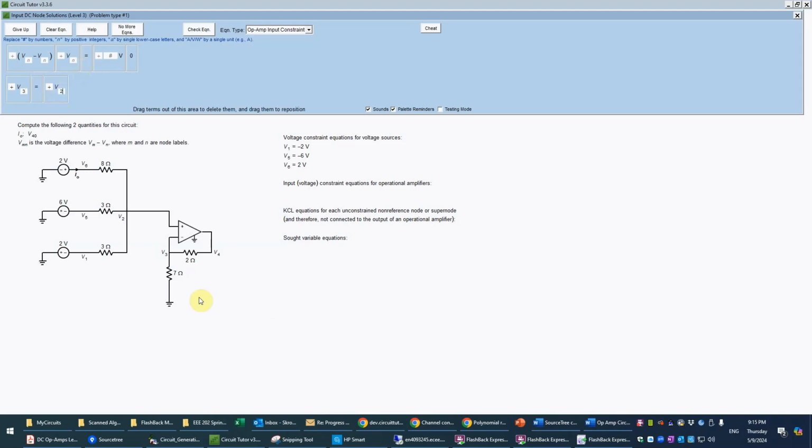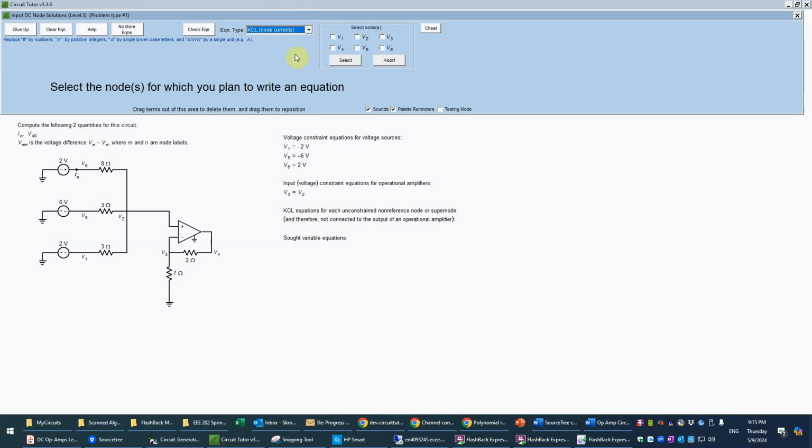But we don't know either value, we just know that they have to be the same. Okay, so that is correct, and now we have to do the central equations in any nodal analysis, which are Kirchhoff's current law equations, expressing the fact that the sum of the currents entering or leaving any closed surface has to be 0 in a circuit. And the surface can enclose a node or could even be a supernode in some cases.